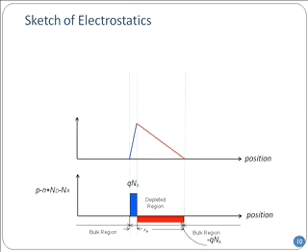Now this statement where the blue and the red are the same in the junction, that only happens for a very special case, which I will explain in a second: if both sides are silicon. But if one side is silicon and another side is germanium, you cannot make that blue electric field and the red electric field continuous at the junction. I'll explain in a second.